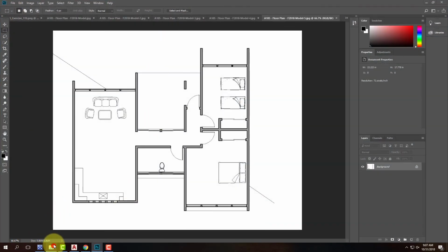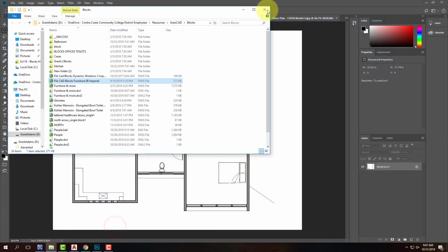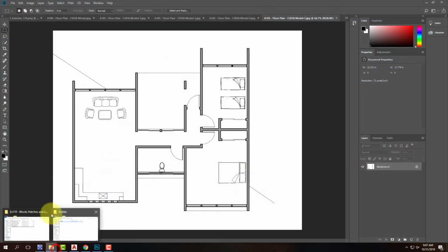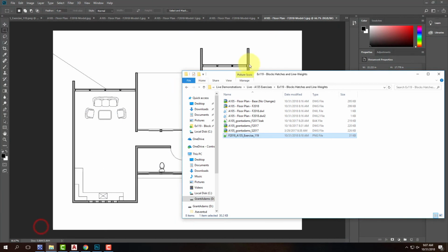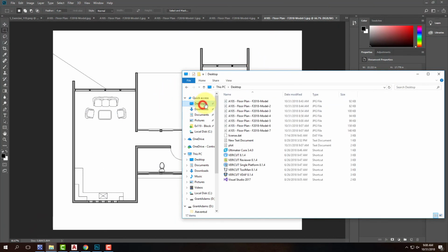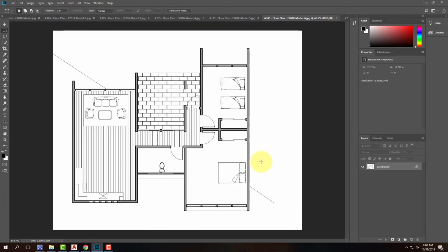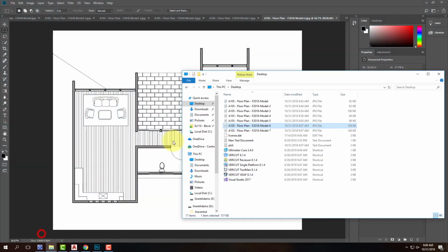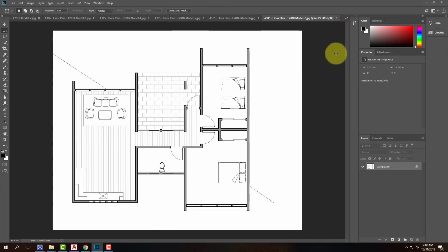So let me open up, oh, it's on the desktop, sorry. 6. So there it is where the hatch patterns are black. So they're really showing up. And you can see here that those lines didn't show up in my doorways because they were on that non-printing layer. They're not there. That was a little strong. So the option would be this one, which was number 7, where those are much fainter.